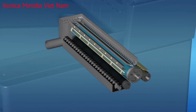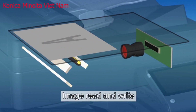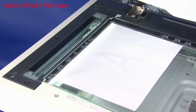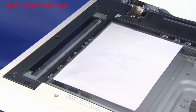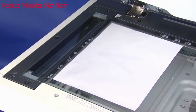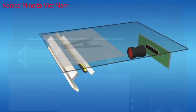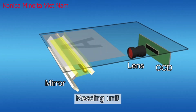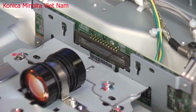The next process involves reading and writing of the original image. When the original image is exposed to light, the black areas absorb light and the white areas reflect light. The reflected light is conveyed to the CCD through a mirror and lens. Next, the image information for the original is converted from an optical signal into an electrical signal. These procedures are performed by the reading unit.